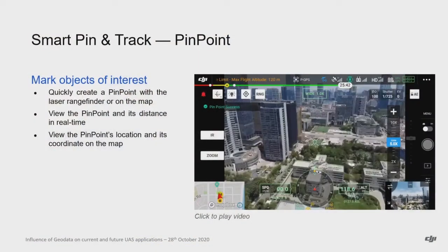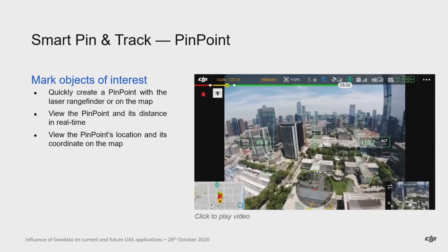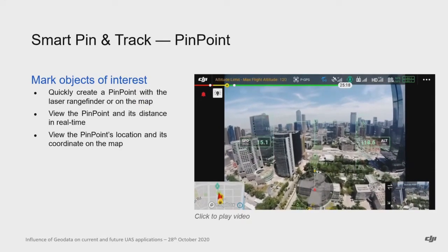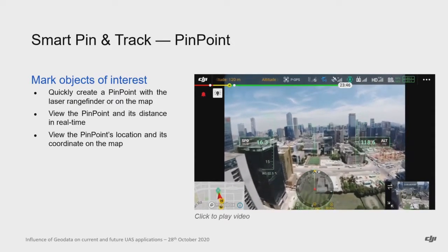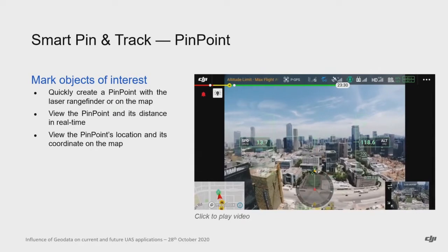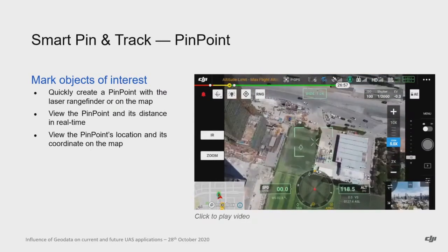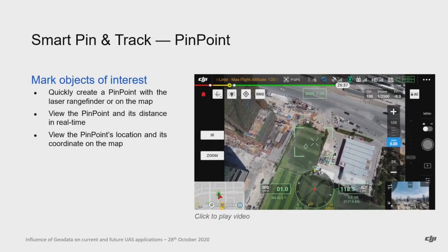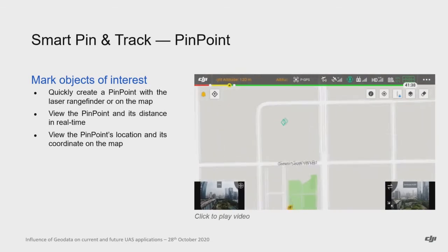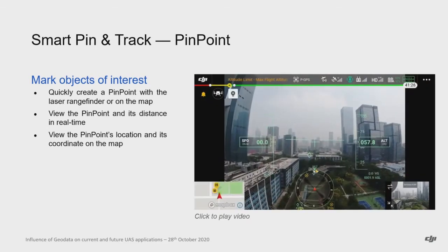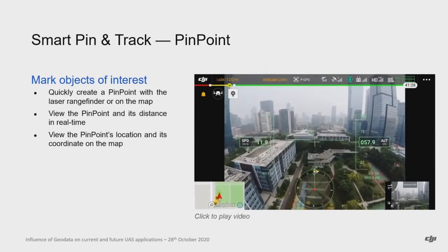And then we are coming to the combination of the information. So we are having the geodata as an information source for the mapping. We are having the accurate GNSS and RTK positioning information. And then we have the classic way of control. But what can be combined? For the way I control the drone, I can mark points on the map or on the display where the drone should be flown. And this then starts an automatic maneuver where the drone is actively maneuvering to this point, which is located in the map. So it's a combination of both.